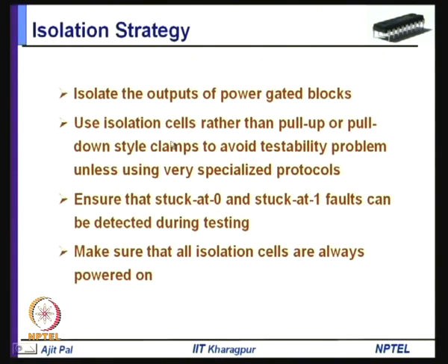However, there are some strategies which are used to make the circuit foolproof. You have to isolate the outputs of power gated blocks, and use isolation cells rather than pull up and pull down style clamps.